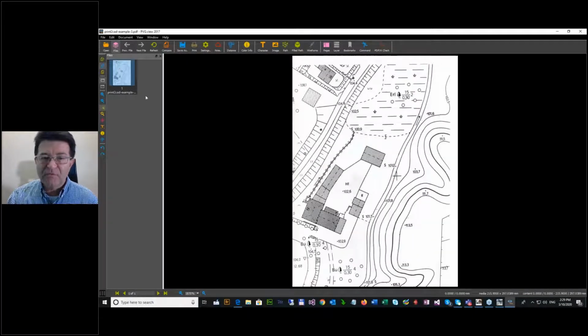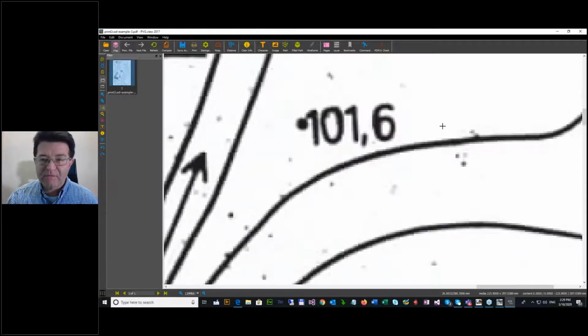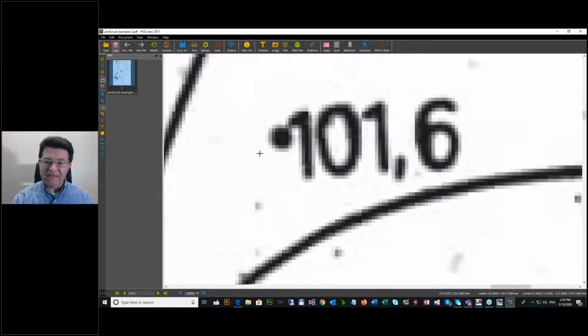Before you start the separation with raster to vector, we need another very important parameter: the threshold for the color black, because every vectorization is made only on a black and white drawing. This is not a black and white drawing. This is a grayscale drawing.